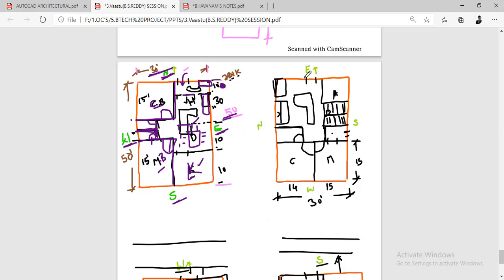If it is an east facing house, see, we already discussed staircases, we need to provide them in the southeast side or northwest. Somewhere here I need to provide, and northwest as well. How we can climb the staircases, just remember it is clockwise. Clockwise we need to provide. If you provide it from bottom to top, this rotation will be clockwise, so that's why you need to consider how we can climb it. That indication also you need to see, this is up, we can climb from here, and that will be a clockwise direction.